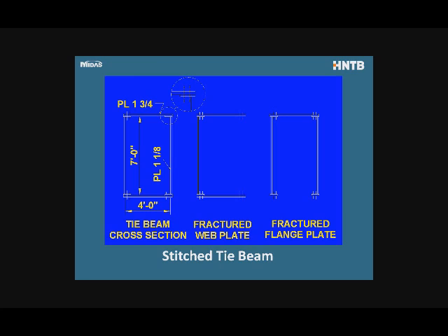This is where the ductility or the insensitivity to bending moments comes in too, with the network tied arch bridge. So we can afford, we don't really need the moment capacity of the tie beam with network arrangement. Now the idea of the bolted connection is that if any one of the plates fractures, that fracture would be arrested at the bolt line, and so we would not have a progressive fracture throughout the entire cross-section.